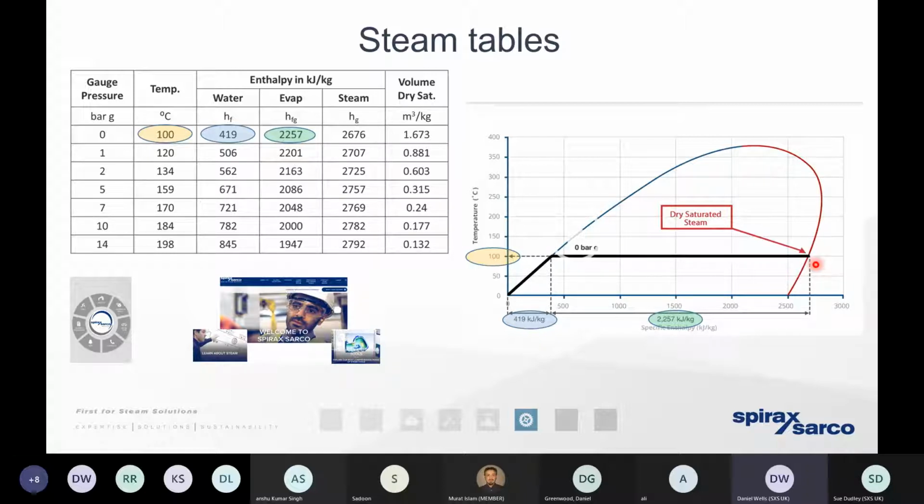And if we're holding condensate back, we're at risk of erosion, corrosion, water hammer. That's when water exists within an infrastructure that's been designed to accommodate steam as a gas. And as that energy is released very, very quickly, as it's conveyed around the network at some speed, that's when we get a lot of crash banging, water hammer, vibration, damage to capital equipment.